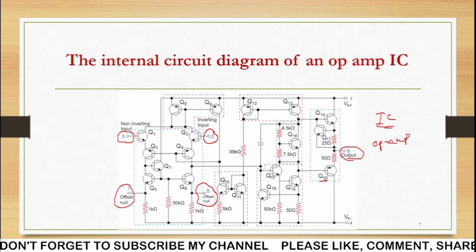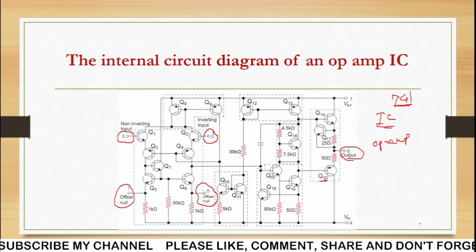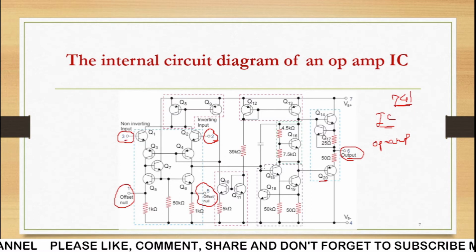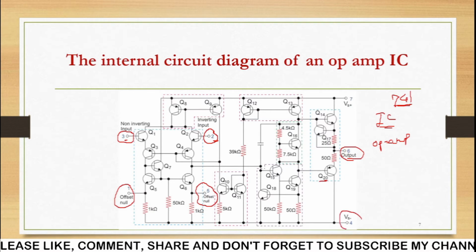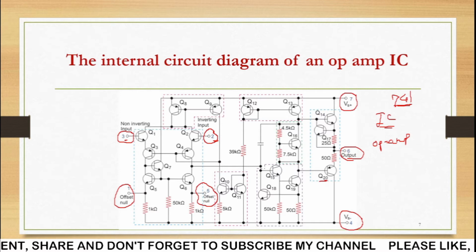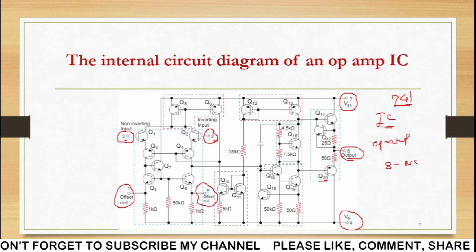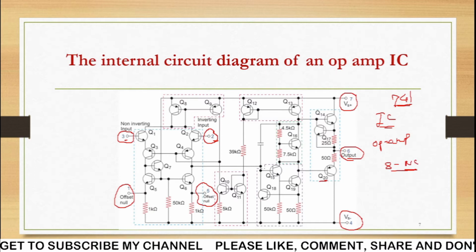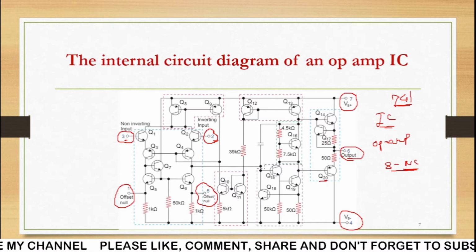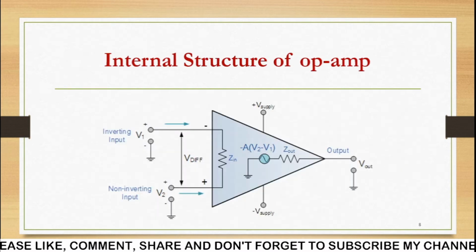You can see here the first stage is the differential amplifier stage, the second stage is called the amplifying stage, and the third stage is called the output stage. So there are three stages, using almost 20 transistors with resistors and capacitors. Pin number 4 is connected to the minus supply and pin number 7 to the plus supply. In the case of the 741 operational amplifier, pin number 8 has no connection, so out of 8 pins, 7 are used.